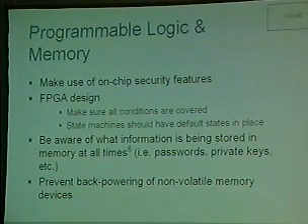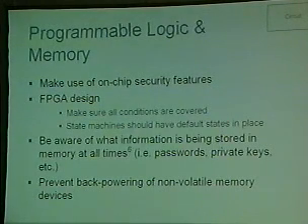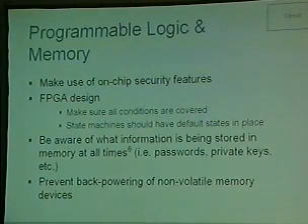So when you're dealing with your programmable logic and memory, you want to make use of all of your on-chip security features. There are security fuses and software protection bits and software protection strings that you can send to the device and make sure that it won't leak the data. It will disallow somebody from reading the contents of the memory. Although there's sometimes ways to bypass that fuse, for example, deleting and viewing the die, which I mentioned earlier, which is popular in smart card attacks and mentioned in one of Marcus Kuhn's papers that I believe is a reference. You still need to take steps to protect the firmware as well as you can.